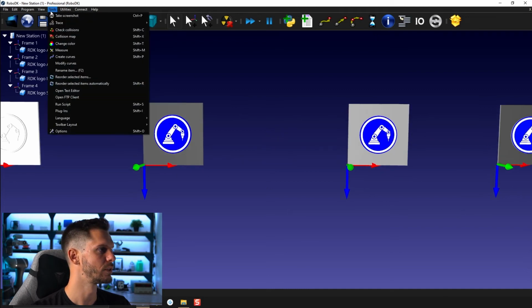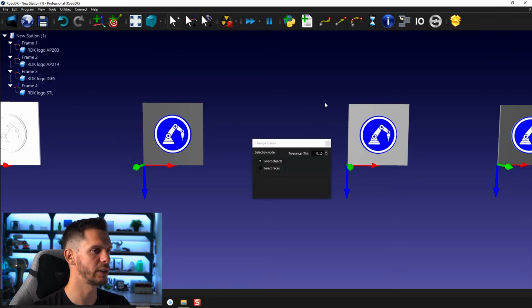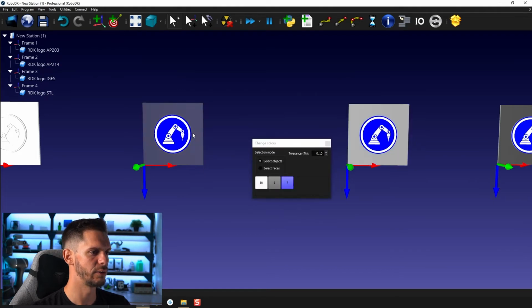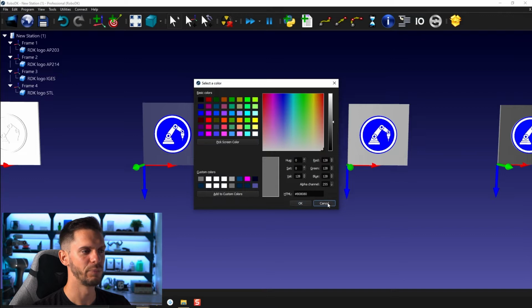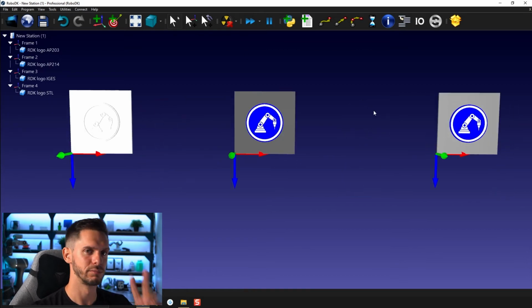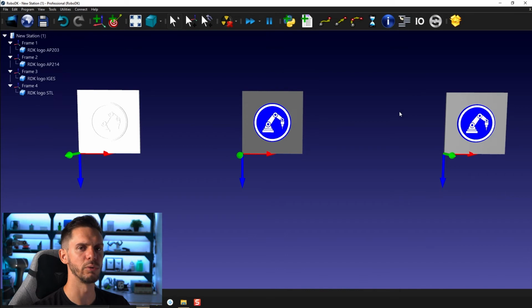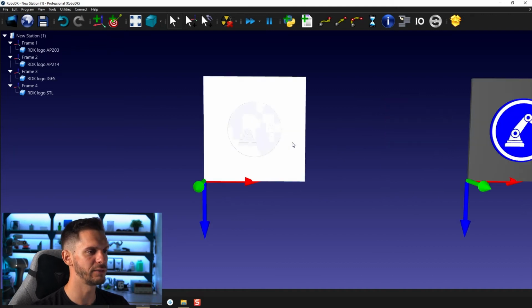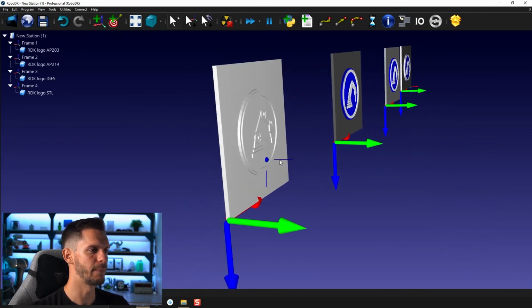So if we were to do a comparison real quick, here the gray is 80, 80, 80, and if you select this one here, it's still 80, 80, 80. And still the color looks a bit different. The reason is that sometimes you have the top surface and the bottom surface, and there's a normal that will change the way light from the software is reflected, and will change the color a bit. So anyway, it's the same color, but it won't show exactly the same because one is an IGES and one is a step file. So here, the final file format we have is the STL.